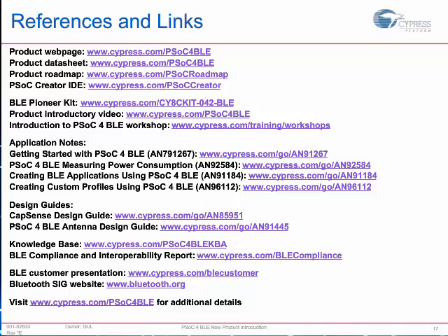We also have a special jumper on the dev kit that's dedicated to measuring power consumption of the chip. It isolates the PSoC 4 BLE chip that's on the dev kit from all of the other things that are on the dev kit. You can stick a picoamp meter, for instance, across that jumper, or a simple ammeter, depending on what types of currents you're measuring, and see your real-time power consumption as your product is being developed and being debugged. As you switch between power modes, you can see in real time what your ammeter is showing for power consumption.